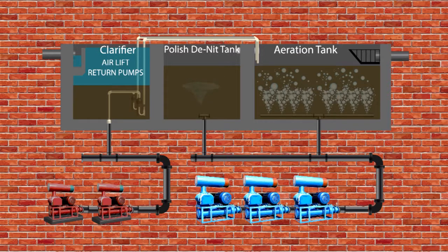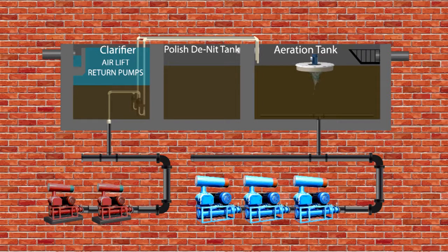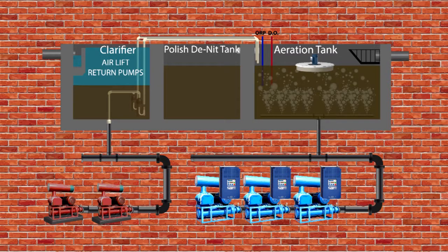After reviewing the site drawings and based on average influent flow, there was more than enough detention time to continually cycle the tank between nitrification and denitrification. A floating mixer was installed in the tank to provide continuous biomass mixing while the blowers were turned off during the denitrification cycle. The ORP and dissolved oxygen probes were installed as close as possible to the tank discharge pipe to get an average sample of the processed water as it was leaving the tank. Each blower was supplied with a PLC-controlled VFD to maintain the preset DO level for the nitrification cycle until the ORP target value was reached.